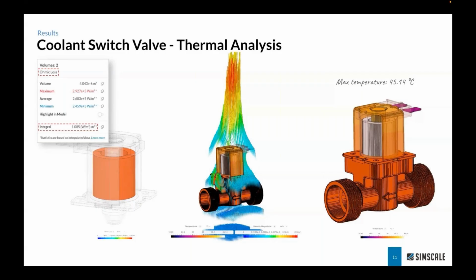Because this is still an early stage design scenario, I chose the immersed boundary method within my thermal simulation analysis types, rather than dealing with a body fitted mesh, because this approach allows me to quickly iterate on the thermal behavior without needing to do any CAD cleaning or having my model ready for simulation. This is a major time saver for initial exploration and optimization of my design.